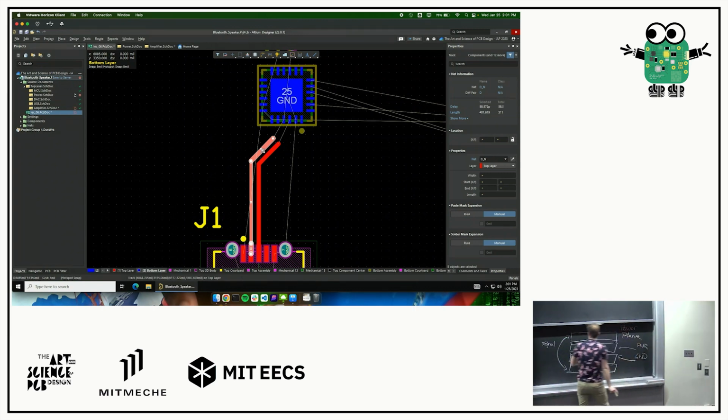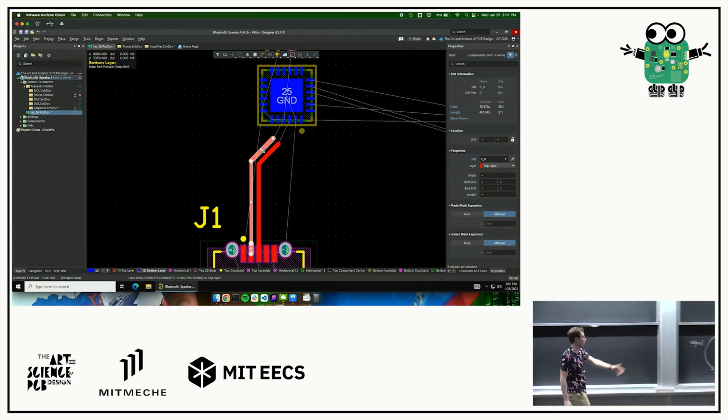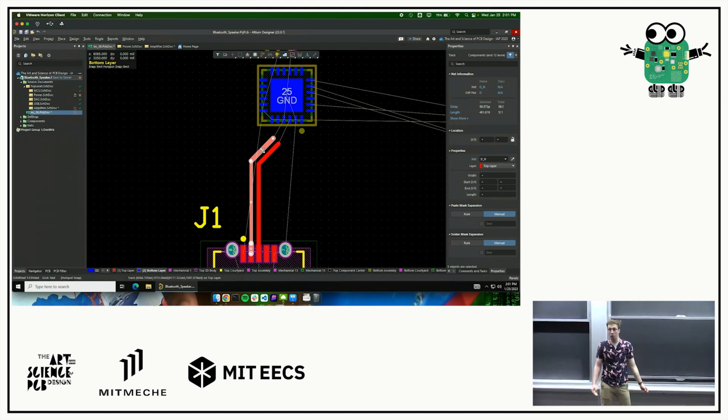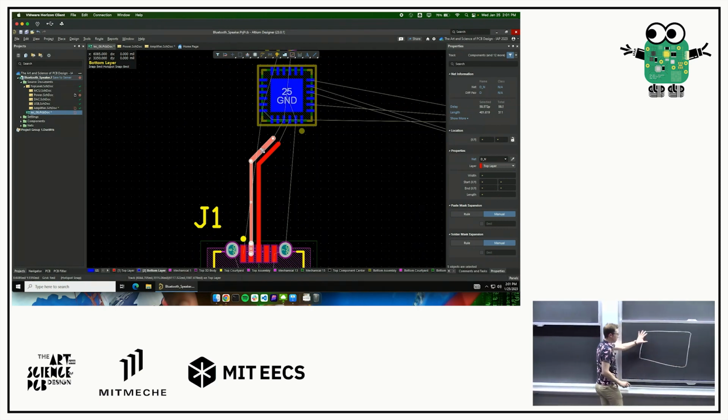which these are, because the entire layer, the entire plane, is either power or ground, instead we'll settle for something called a ground pour or a power pour. And that's different because, let's look at the top view of a board here. Let's say we have our top layer copper, and we have a bunch of parts that need to connect to each other, and so on. They have all their signals routing between them. Maybe this goes to some component over here. We have all of our signals up here living inside of the top layer.